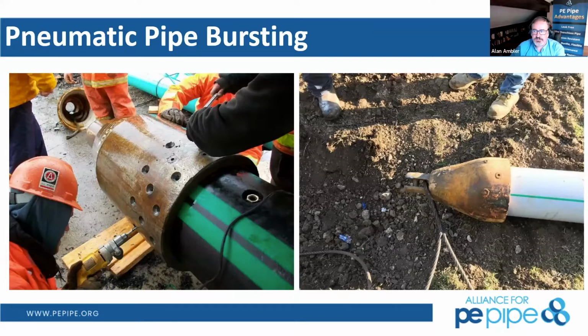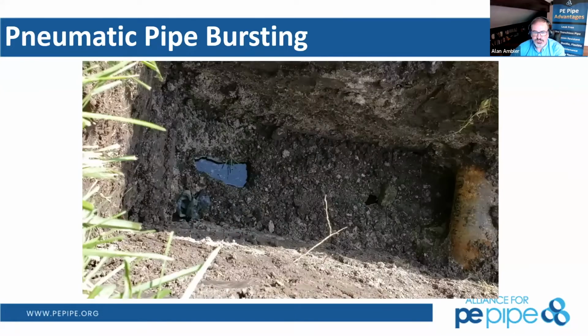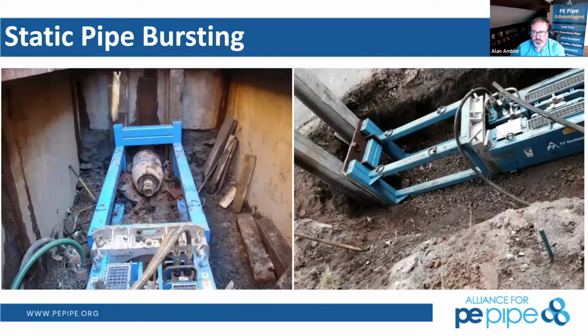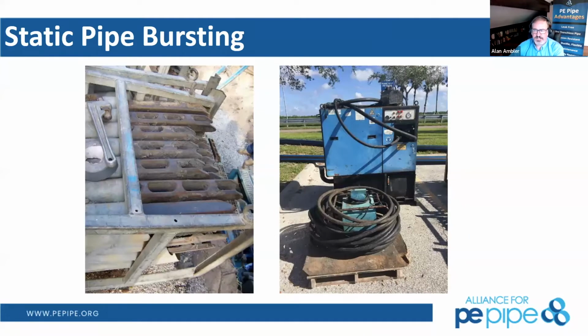Absolutely. One of the beauties of working with HDPE is how rugged and durable it is while we're working with it. So anything that the contractor may have used to screw into while we are doing the operations would be cut off, and then we'd fuse to final connections or use other connections there.